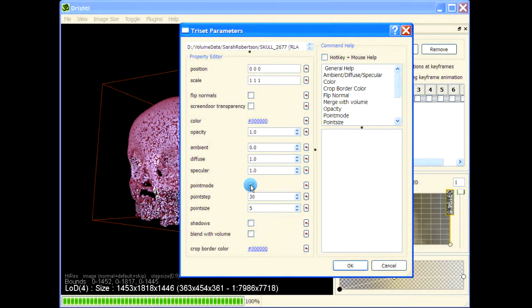Now this mesh has color per vertex, so each of the vertices or each of the nodes in the triangular mesh has color, and then setting black color here, setting 0 0 0 for red green blue will bring on that color. Otherwise whatever color is chosen here will be shown on the mesh.